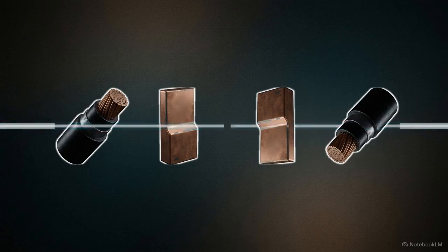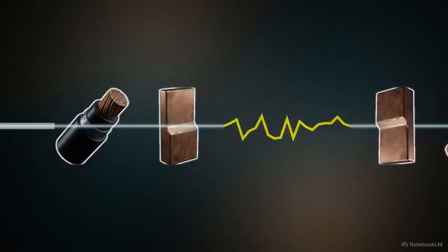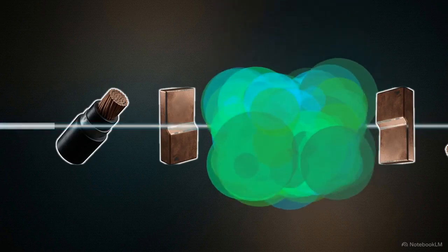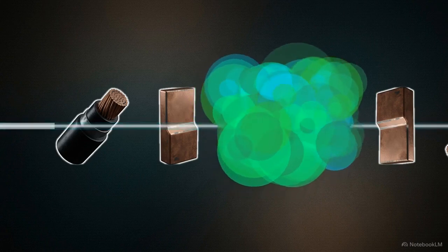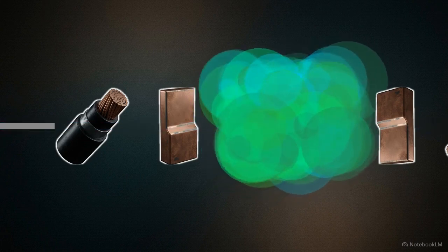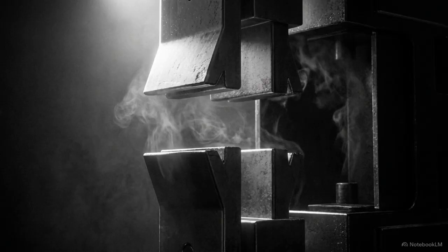As the contacts separate and the arc forms, the breaker blasts the gap with a non-ionized medium, like a total vacuum or sulfur hexafluoride gas. The gas instantly strips the charge from the space, suffocating the arc. This brutal, lightning-fast physical separation is the only mechanical action capable of arresting the fault's exponential heat and saving the power lines from total meltdown.